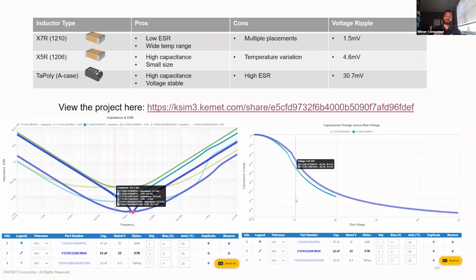Metal composite inductors are the preferred choice because of their temperature stability. With ferrites, you can get, as I said, more inductance, but they start to deviate as you increase in temperature, more so than a metal composite inductor option. Okay.